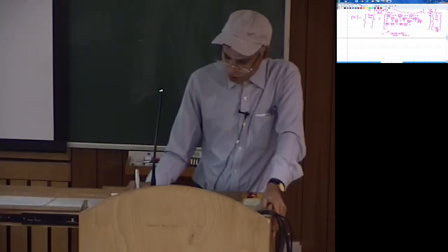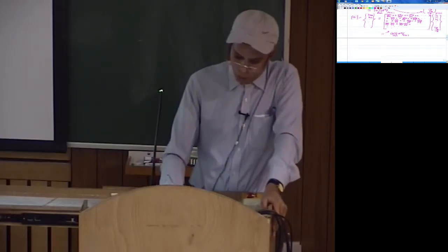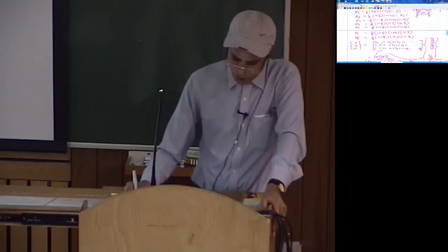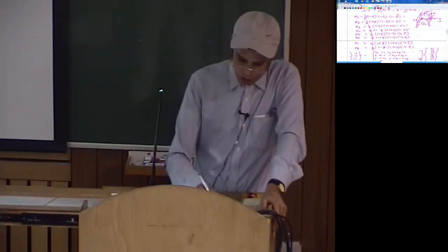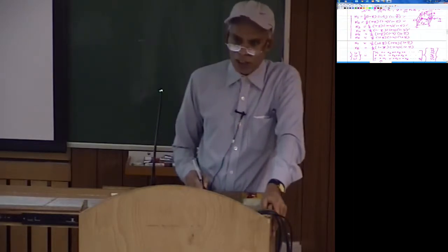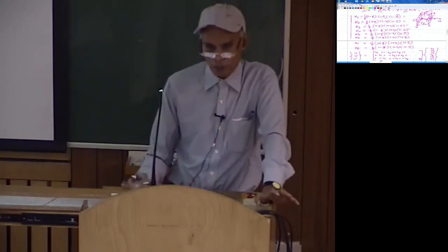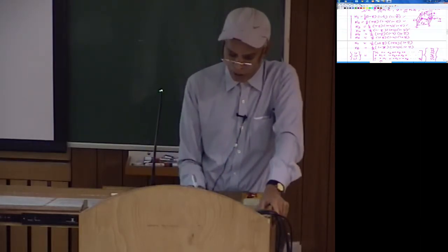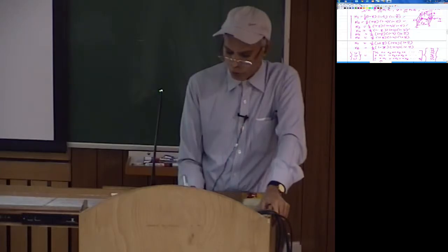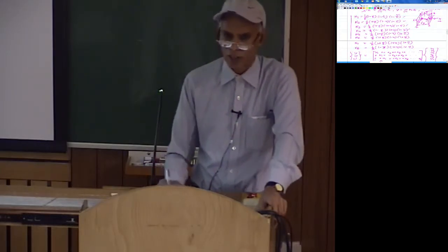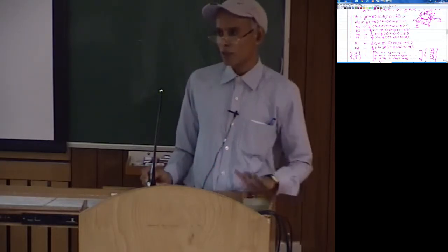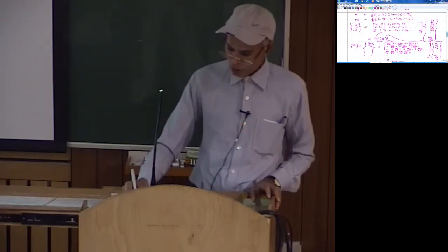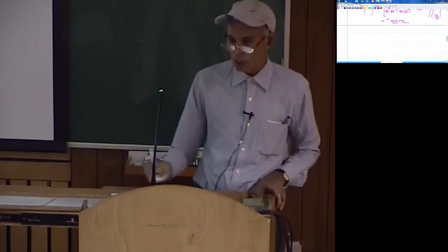Now before we substitute this, I also want to look at how we will be evaluating these derivatives. As far as the shape functions are concerned, we have written them in terms of xi, eta and zeta. We can find their derivatives explicitly with respect to xi, eta and zeta. For example, del N1 by del xi would be minus 1 by 8 into 1 minus eta into 1 minus zeta, like that. So you can get their derivatives directly with respect to natural coordinates, but then you finally need the derivatives of these with respect to x, y and z, the physical coordinates.